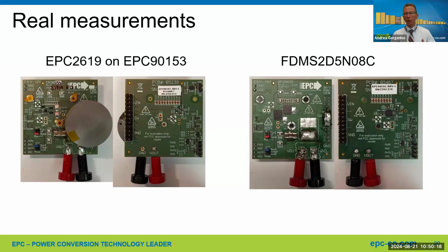I'm thinking about Spice. Spice by itself will give you a number, but it's not going to match your real number unless you model your full system, including all the parasitics. I mentioned some of them, but if you want to get a really good match, you need to include the models for all of the components that are relevant for the power conversion stage. Once you have that, then you can use Spice tools to do worst case, but that's not implemented as of today.